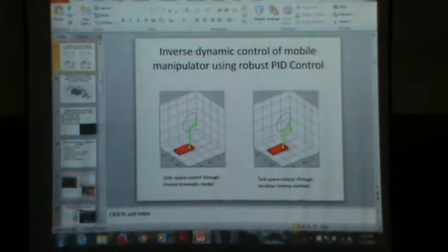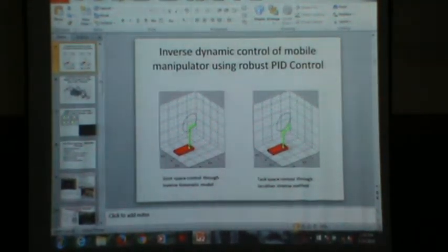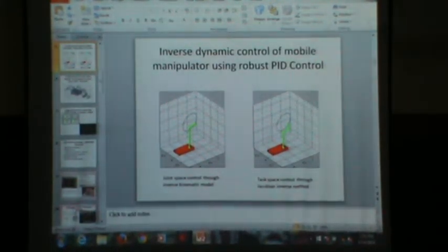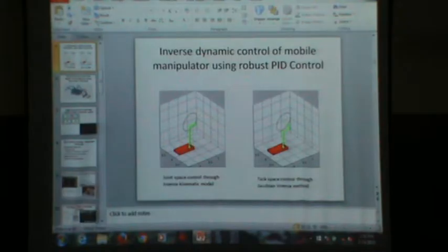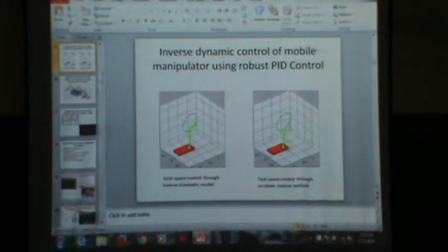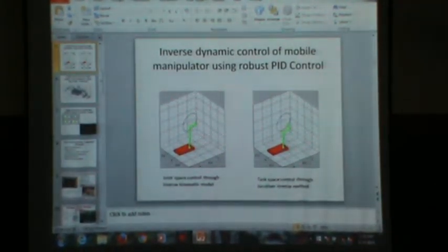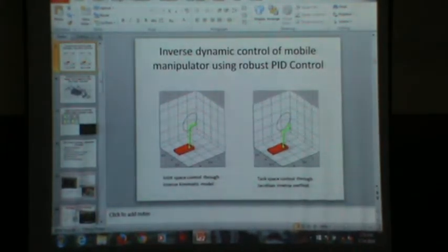But if you are working only in joint space or only in task space, like what I did earlier, that has a problem because it depends on the Jacobian, and you have to convert. I call this the force required. It needs to be compared and converted to joint space motor torque or motor forces, so this conversion is required. But in this dual loop, this conversion is not required, because you are deriving only a virtual velocity vector. It is not much trouble compared to this conversion. This way we can end up with the dual loop, which will be very beneficial to us.